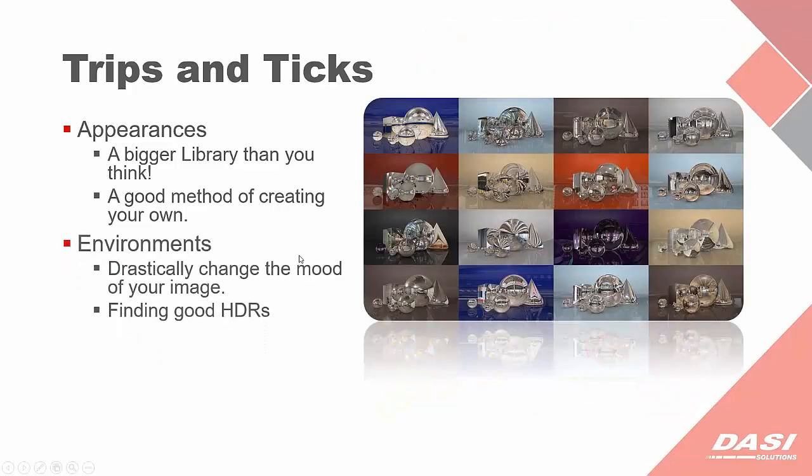All right, environments. Environments are the next thing that really has a lot to do with the project that you're rendering out. Obviously, how the part looks is going to be important, but the next step after that is really what's the environment that it's in. Here you can see that I've got the same model listed 16 times with the same material, the same appearance, but you can see that the background is drastically changing the mood and the look of the image.